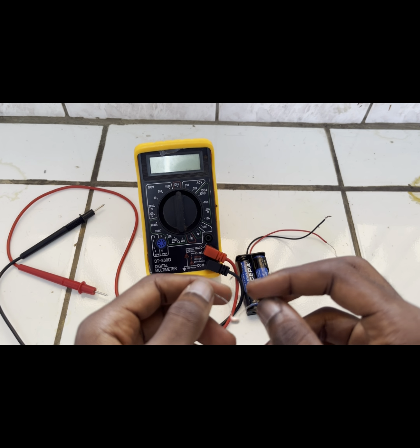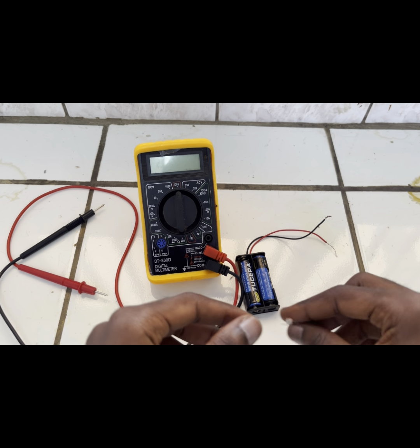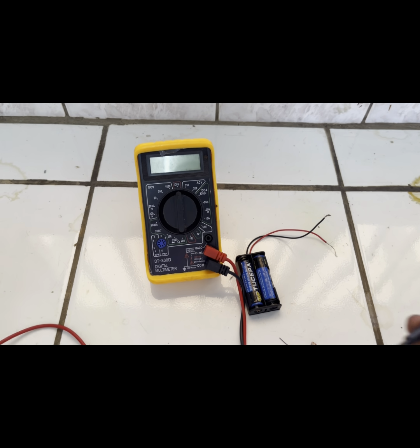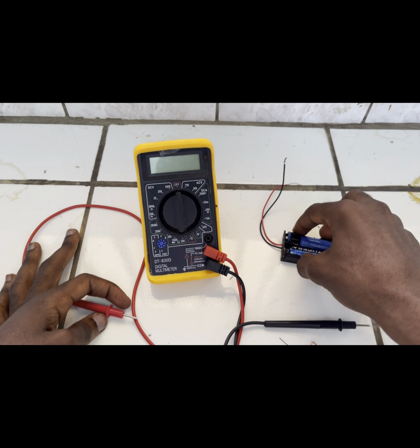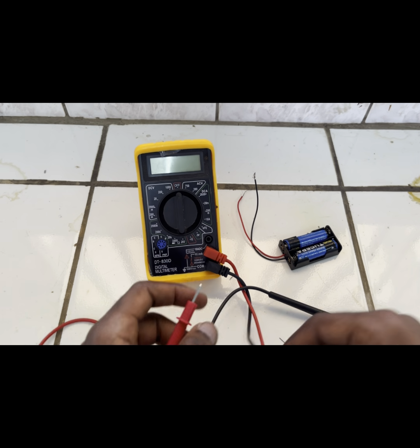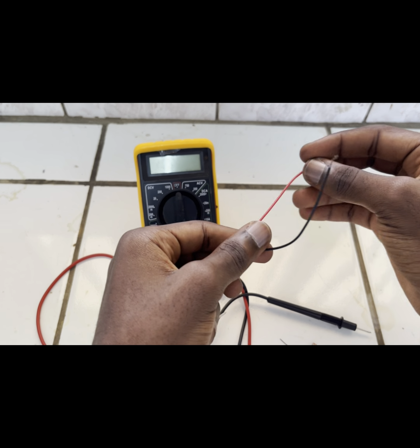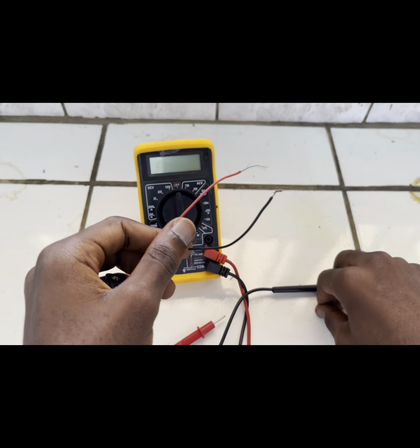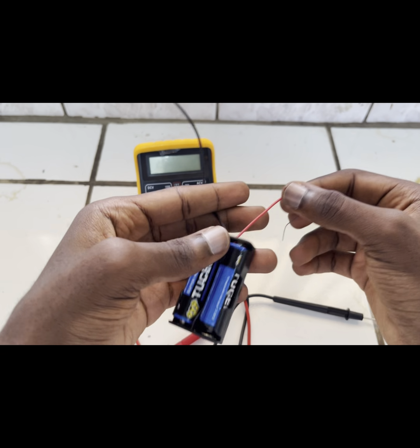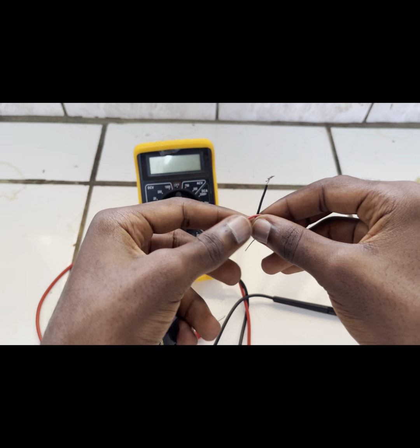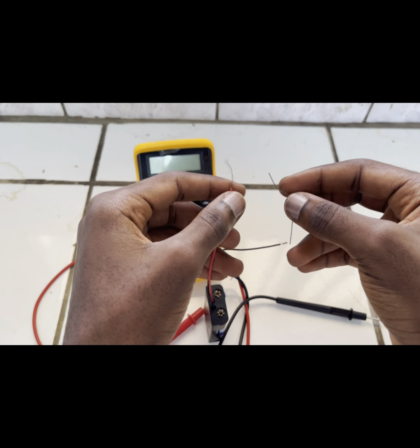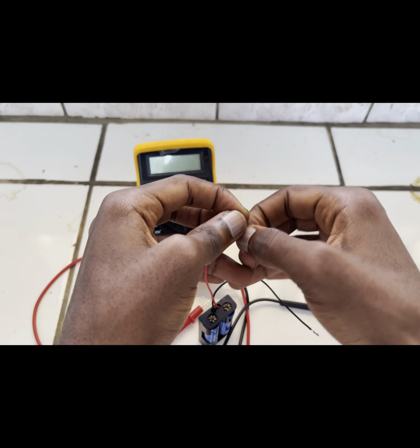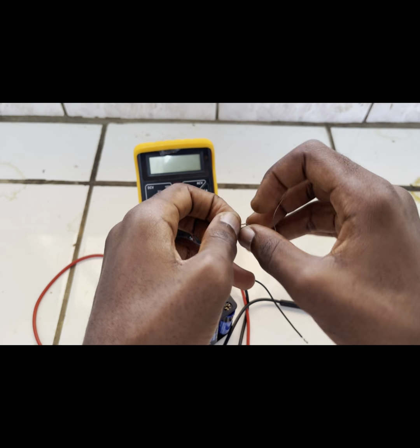Now, the first thing that you should know here is how we connect an ammeter in a circuit. An ammeter is always connected in series. In a circuit, you should know how to do a series connection. A series connection is not a parallel connection. So you are supposed to take your battery. You take one terminal of component H and connect it with one terminal of the battery like this.